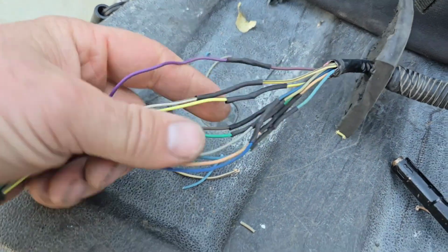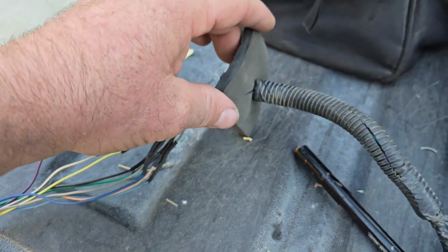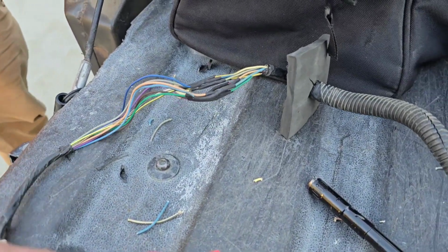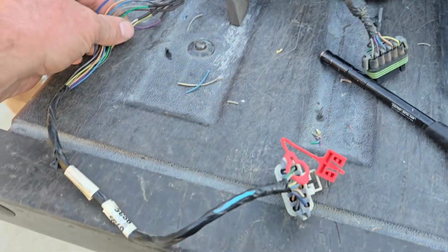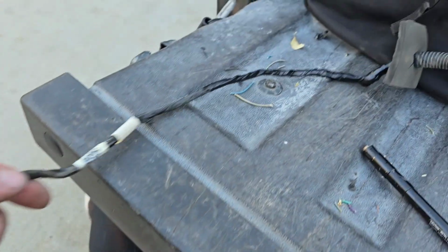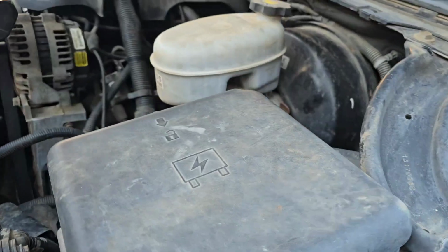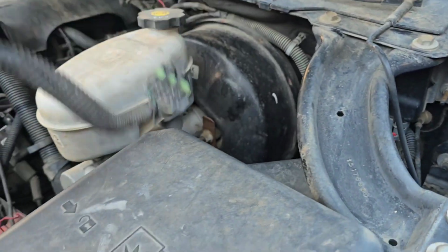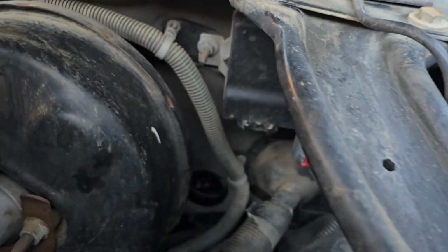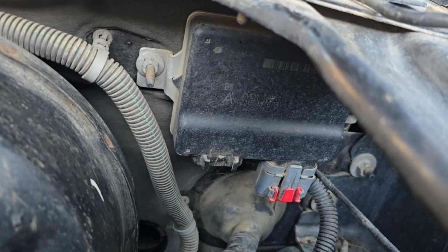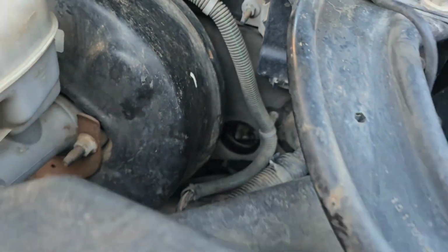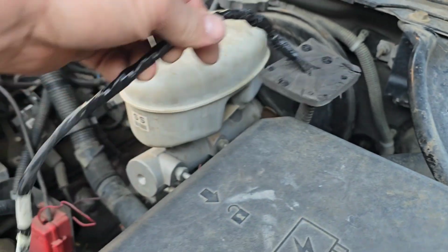Alright, heat shrink on. Made a little custom grommet out of an old shoe. Zapatio? Zapata. Tennis shoes, yeah. Okay, ready to go. What's really nice about this repair specifically is you can see this is the outside. This goes right here to the, I would assume this is like a TAC module because the ECM's down here. Disconnect it from here, pull it right out of there. The grommet was already chewed, so I don't even need to be crouched over.